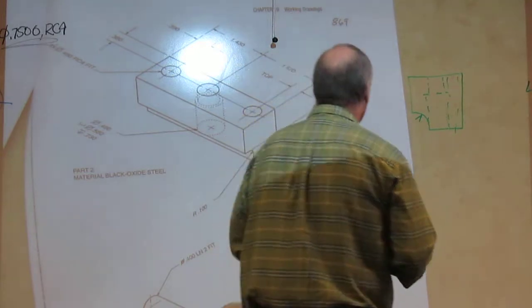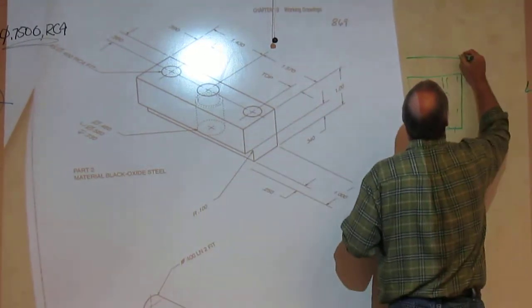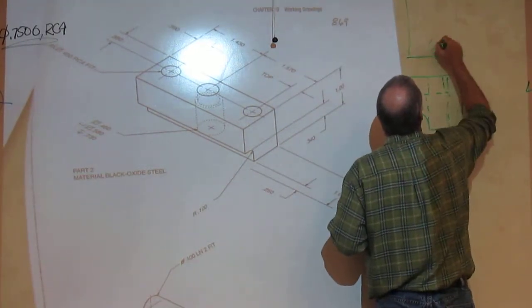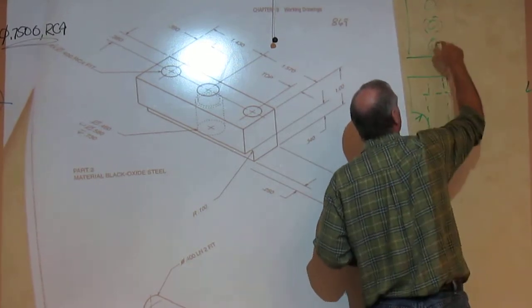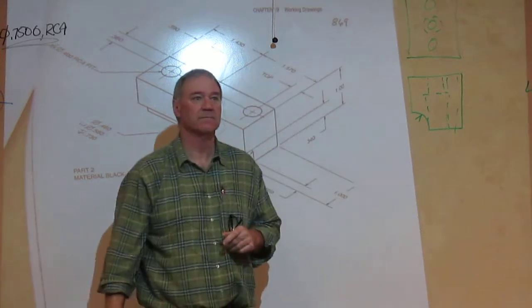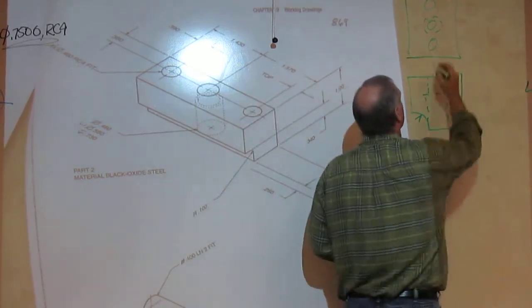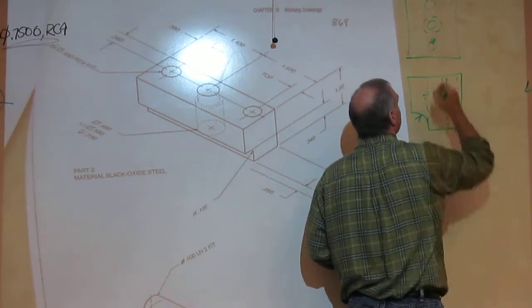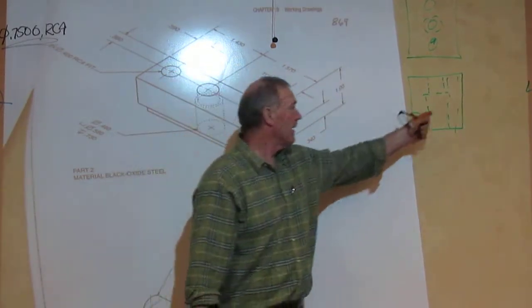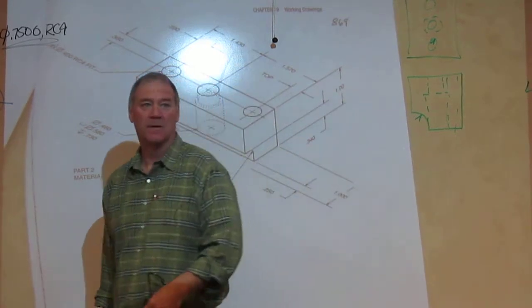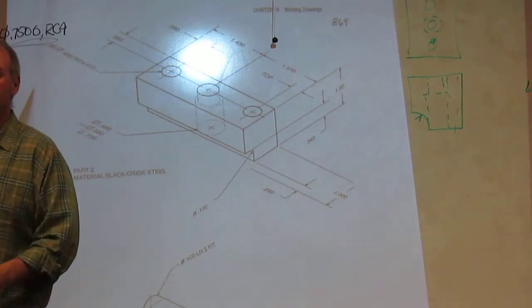When I get to the top view of this thing, I've got a circle, circle, circle. Are these two finished? Are they mating surfaces? Yes, they are. So again, I would have that little V sitting in there because I see the edge view there. I don't put on hidden lines. Do you need to put one on the outside?